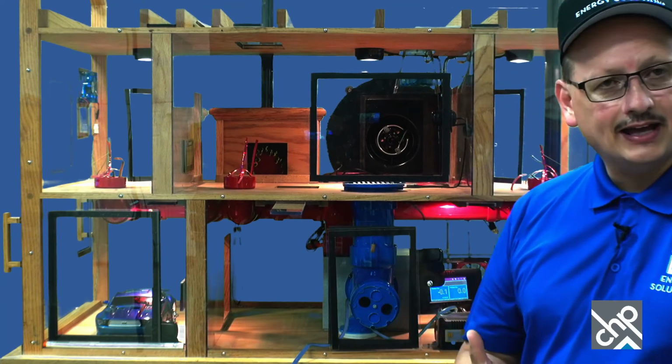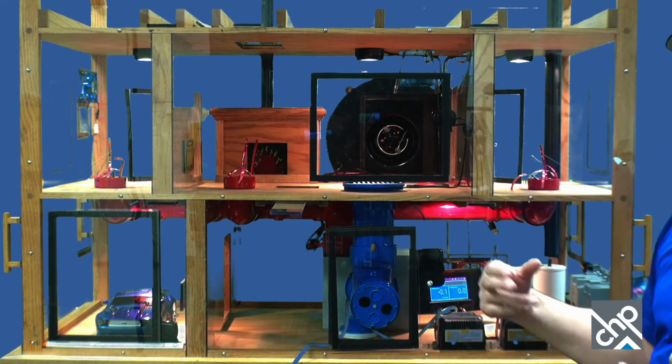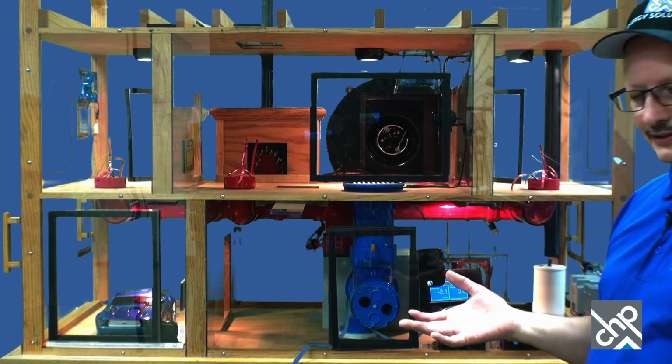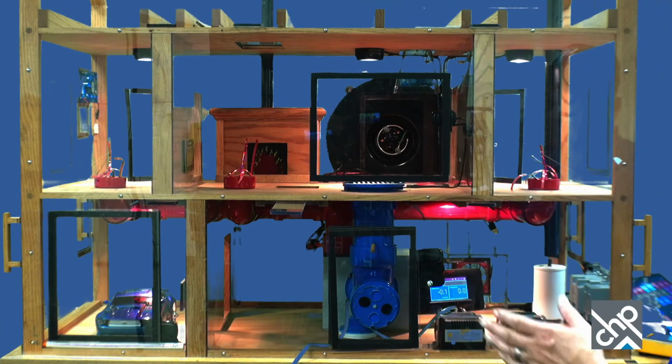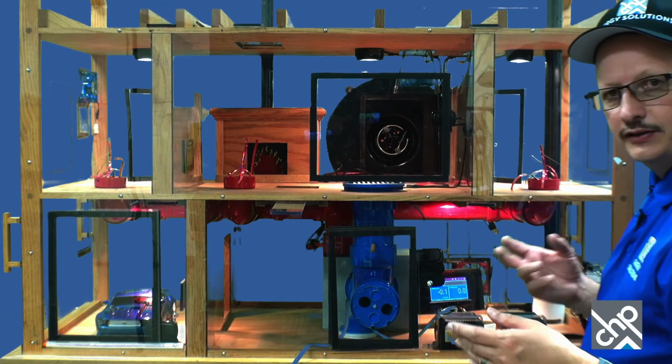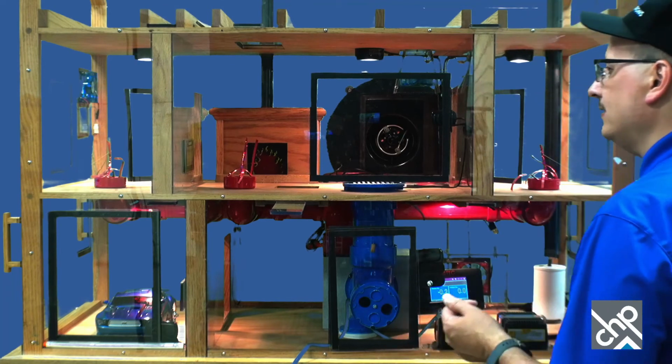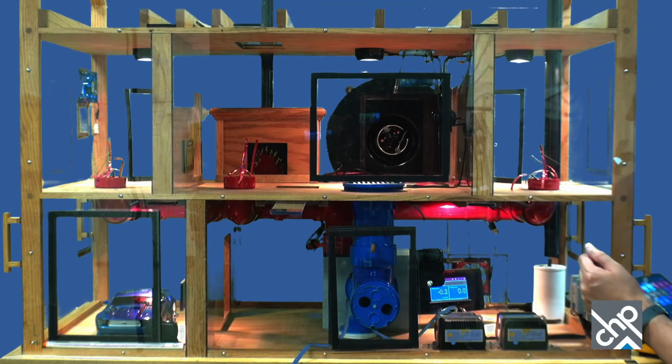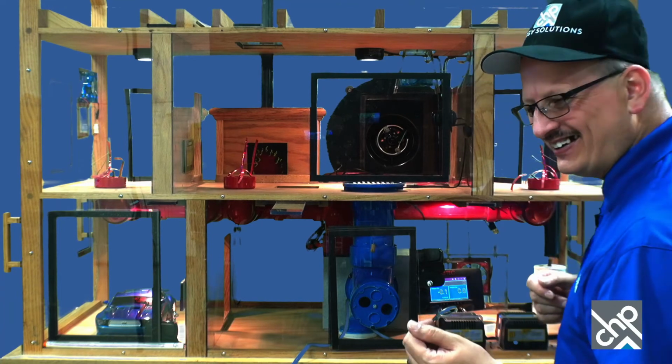You do your baseline test. I'm not going to go through the steps for that here, but I've talked about that enough now. So got the exterior house set in winter mode. Everything's off. Natural conditions. Blower door's up, the covers on the fan, all that kind of stuff. So it's faster the second time, you speed up.